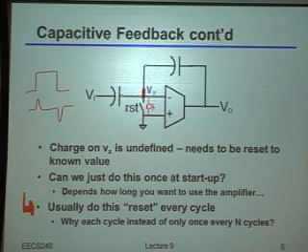So actually, that's really the main reason you tend to do this every single cycle. Because simply by the process of turning that switch on or off, if you're going to create an error, you now have a choice. Either I'm going to create that error, for example, once every 10 cycles, in which case, when I look at my output, every 10 cycles will be corrupted by that error, and all of the other 9 cycles will not, which means I'll see this signal that's repeating at 1 every 10 cycles, or this error signal, I should say. Or if I do this every single cycle, then now what's going to happen? If I repeatedly turn this switch on every single time I sample the output, or turn it on and off every time I sample the output, what's going to happen in terms of that error? What's it going to look like at the output?